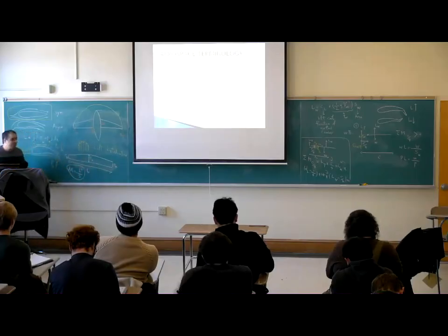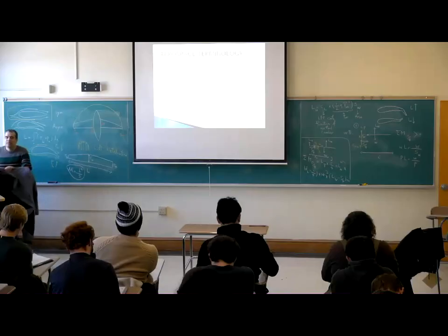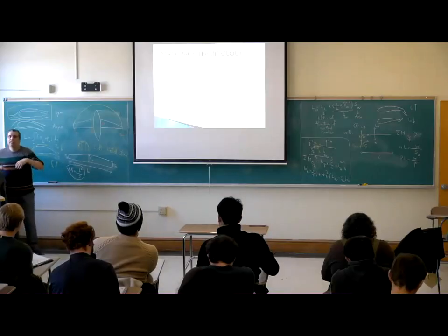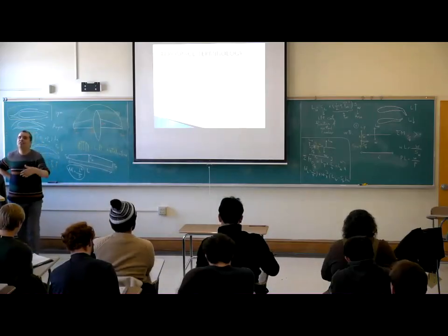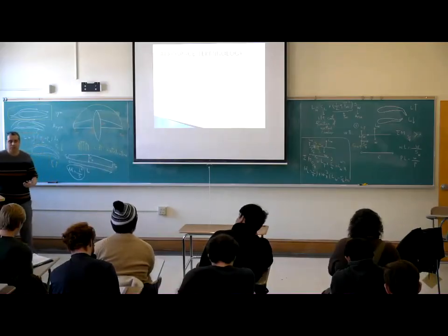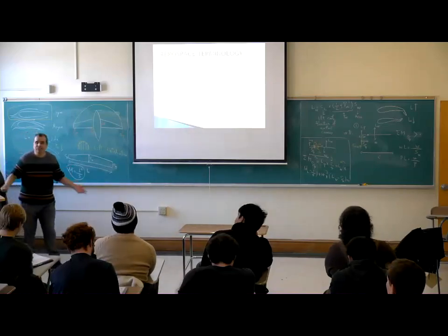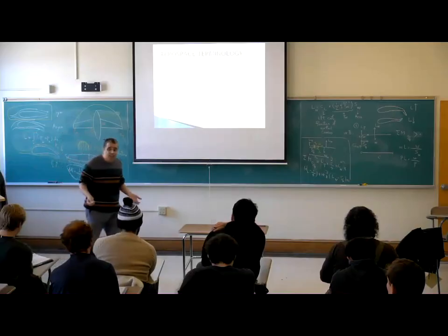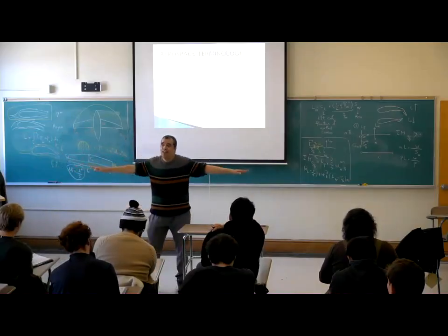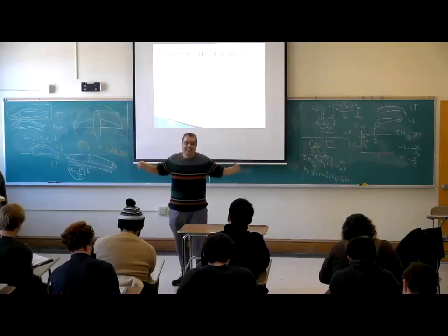This parameter, aspect ratio, appears a lot in the equations that we will later introduce to you. The higher the aspect ratio, the higher the lift. So if you make a glider, you should have a very, very high aspect ratio. You have a very lengthy wing.